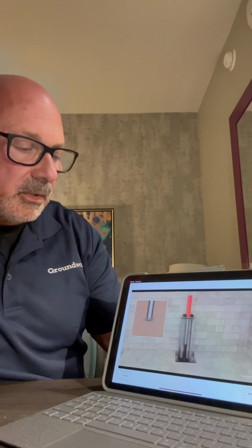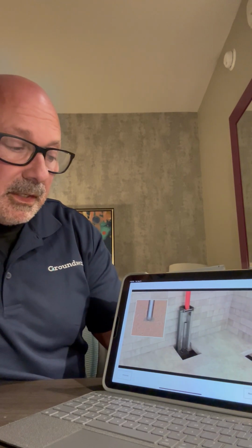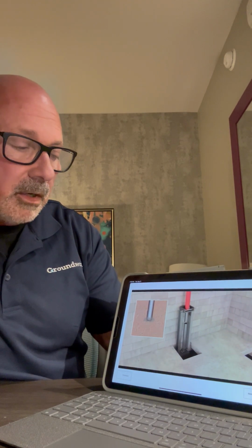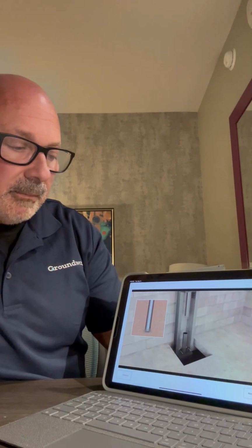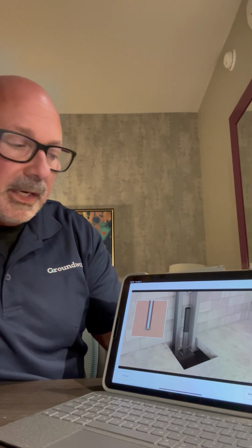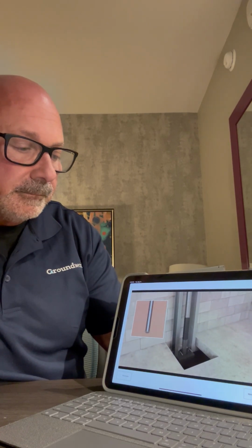And so we continue to add piers. We're measuring the pressure, because pressure will tell us how we're doing. It's not as important as to how far we're going, but how much pressure we have that we're going to be working against the bottom side of your house, right? And how stable it's going to be.